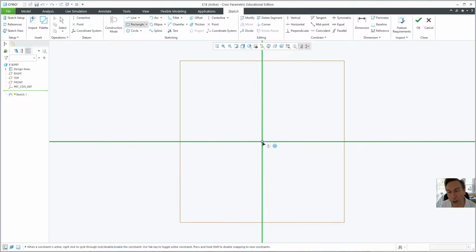Move the tip of your pointer to the center crosshairs. You'll see it will snap. That's your zero marker in space. So you want that to be locked in there. So you'll see little symbols to the right of your pointer. Those are relations or constraints. Coincident, horizontal or vertical, it's going to lock it in. So we are locking in at that point. And later on, we could delete those if we didn't want it there, but that would leave it floating versus it's our anchor point, and that's a good reference to keep.